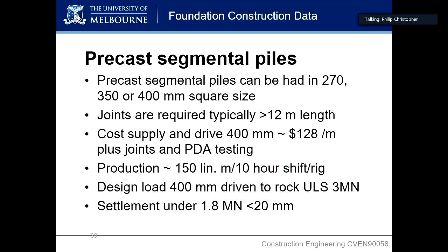All right, the next section is about the estimates around these piles. So let's say you've done some basic estimates on the capacities of precast piles, CFA piles, and bored rock-socketed piles. Your bored rock-socketed pile will be the strongest because it's bigger and deeper into stronger rock. Your CFA pile will be next up because it's not as deep into the stronger rock and it's a bit smaller. And your precast pile will be the lowest capacity, but they're cheaper per unit. So you've got to somehow figure out, what do I recommend for this project? Which pile type? You will know how many of each you need for your bridge based on either serviceability or limit state. Typically, serviceability will dictate the number of piles for your foundation capacity, but sometimes limit state.